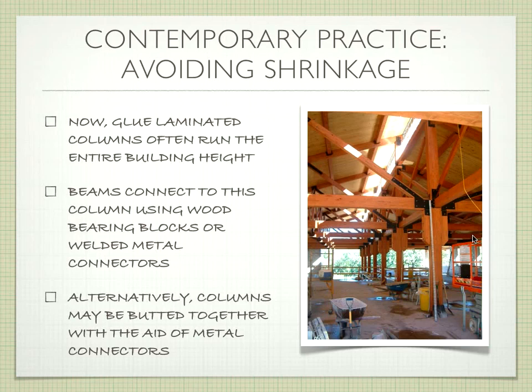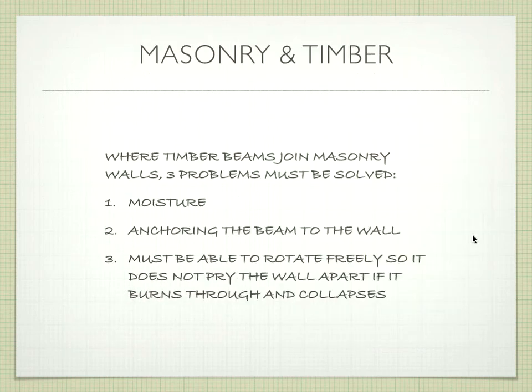Okay? And this, once you bolt it all together, starts to give you the lateral stability that you were asking about. Right? So when we add and meld the steel plates with these kinds of connections, we can start to achieve the kinds of lateral loading conditions that are safe for us to build in, say, California. Right? So we have to think about that.